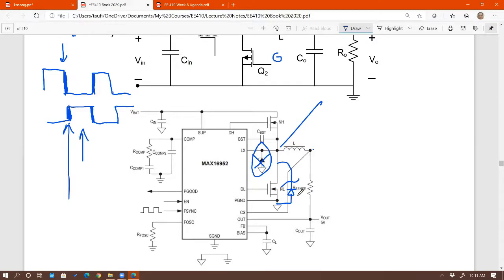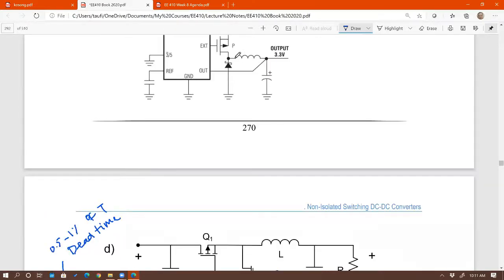But so it's over voltage protection for the FET? Over voltage as well as freewheeling for the energy. Okay. Right. And keep in mind that this Schottky is going to be different from the Schottky that you see here, even though they look the same.